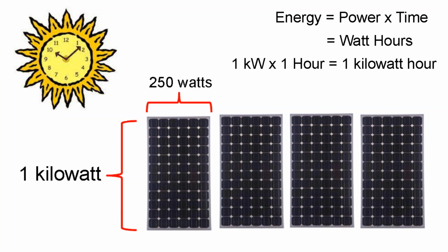So that's more of when you get into markets where you have very limited real estate, like Long Island, New York, you go for the 350 watt modules. If you're in Mississippi and you've got really easy, simple rooftops, plenty of real estate, and you need to go for a lower installation price to make it cost effective, you go in on the low end.